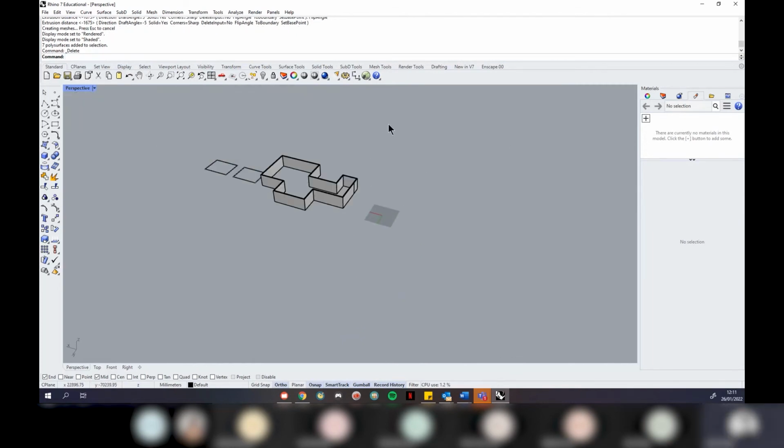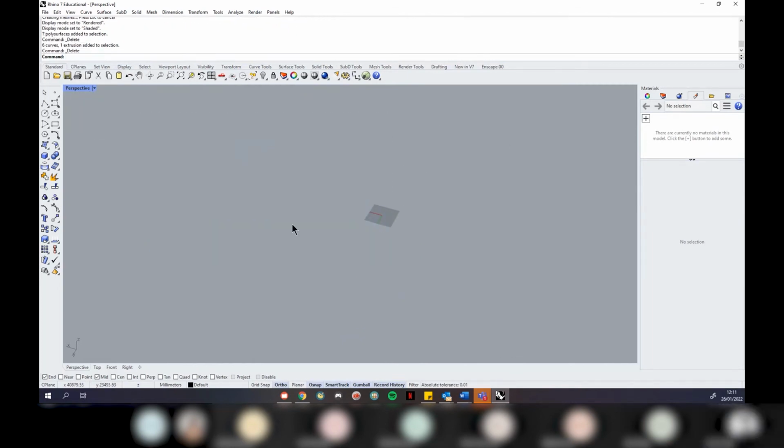Now I'm going to show you how to do surface modeling. This is probably the thing that you all came here for. This is how you can make complex forms, and I'm talking about proper organic forms. This is where it starts getting really fun. What I want you to do is make just a single surface that's a floor plane. The command for that is plane, P-L-A-N-E.